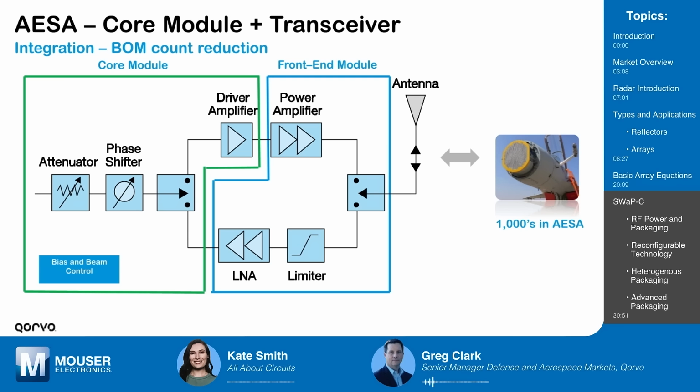These could be SiGe based, they could be SOI based, it could be a combination of GaAs and silicon, but it's combining what I would say are the non-GaN high performance and low noise figure performance needs that you see in the front end module into a core chip that allows you to, again, it goes back to the integration. Instead of having 4, 5, 8 components to 2, that as the system user, you're buying 2 versus 8. Wow, that is actually pretty big jump there, isn't it?